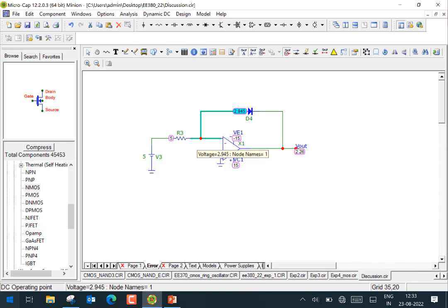So that's an opportunity now to learn that besides the op-amp saturating, there's another thing that can go wrong in an op-amp. What can go wrong, which is true of all circuits, is that every component has a current handling capability, a maximum current that the component can handle. If you try to force more current through it than what it can handle, it will not behave properly. So our op-amp here has a current handling capability of around 20 to 25 milliamperes. Okay, 20 to 25 milliamperes is the maximum current that your op-amp can handle. That is for a 741 op-amp. Other op-amps can handle more or less.